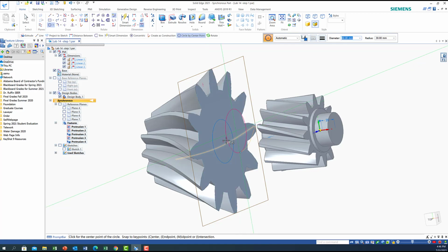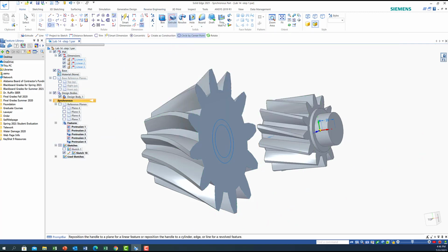And then let's do the 45. Sorry, 45. Enter. So go back again to the same center to be concentric. Okay, now right click. So now I'm going to do the extrusion. So extrusion, chain. So I'm going to get this chain here and this chain. Right click. I need to have this one 4 millimeter. 4. Enter.